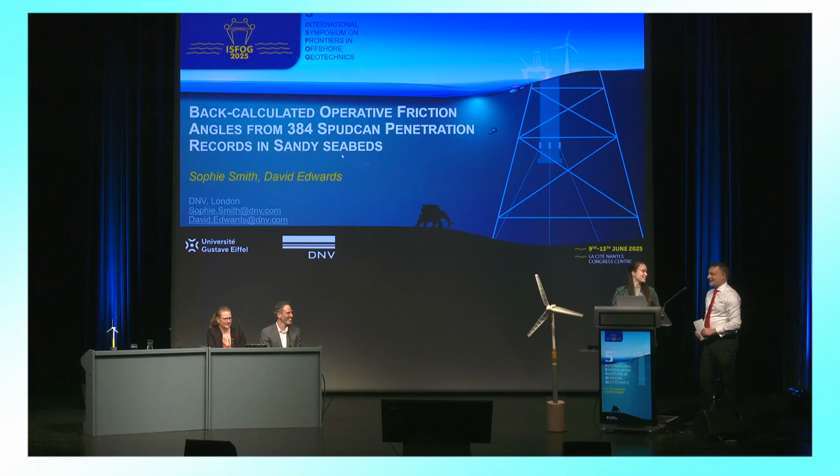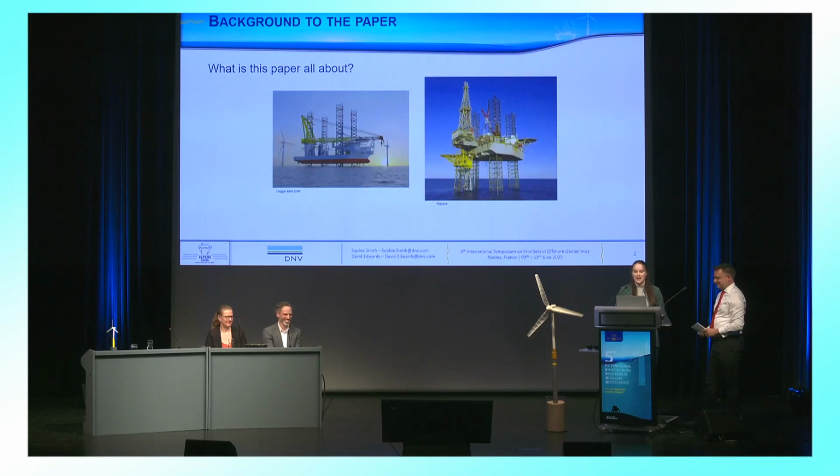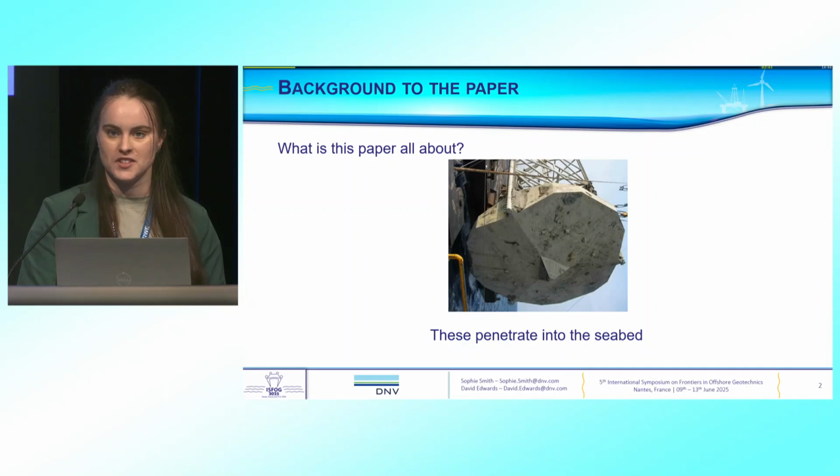Okay, Sophie, what's this paper all about? This paper is all about jack-up vessels, and you can see a couple on screen. We use them in both offshore wind for installing wind turbines and maintaining them, as well as in oil and gas for drilling. At the bottom of each of the legs is a shallow foundation called a spud can, and these penetrate into the seabed.